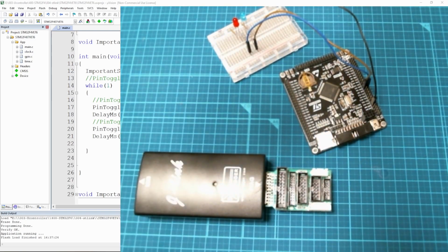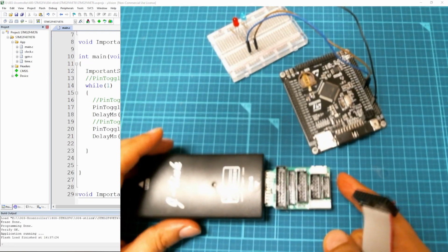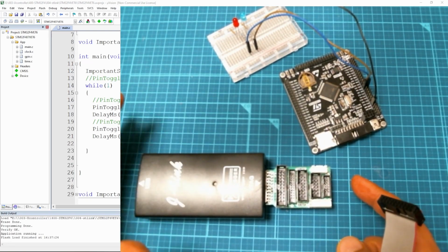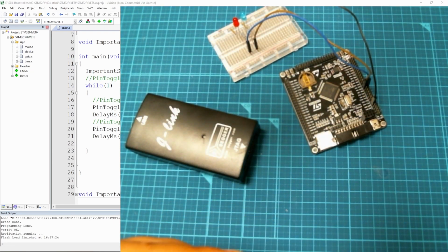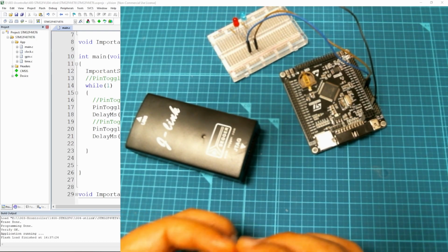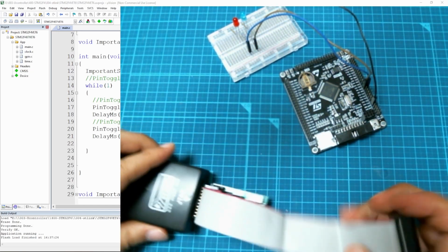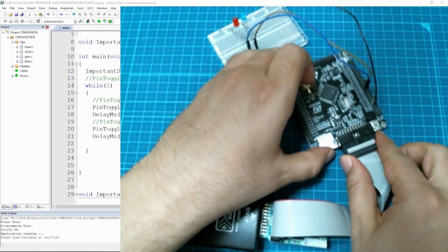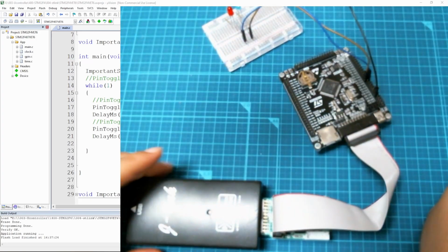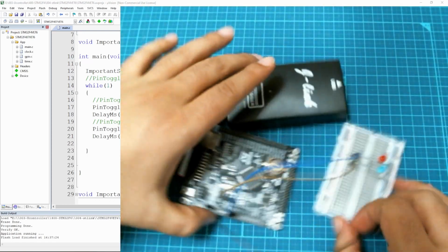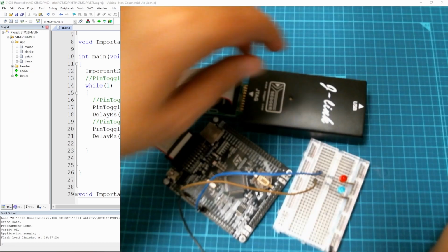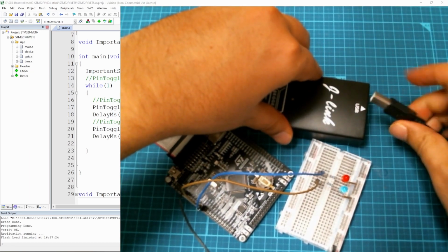After that, you just have to take one of the cables that you have, like this. When you buy this adapter, all the cables and adapters come with it. So that's good. I prefer installing this one first, so as not to put pressure on the pins of the JTAG, and just connect it after that. And then you connect here. Okay, so now let me power this one. Let me turn it like this so it's still visible for you, and put on power.